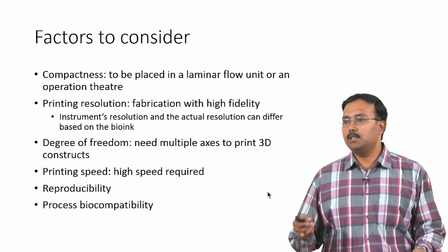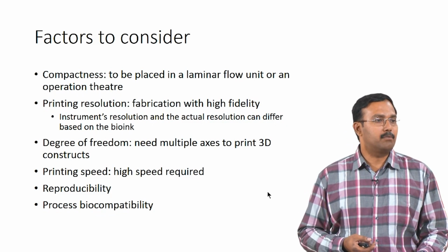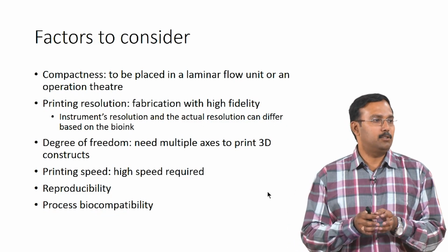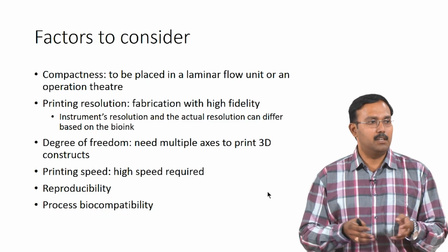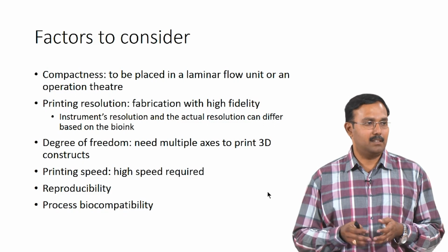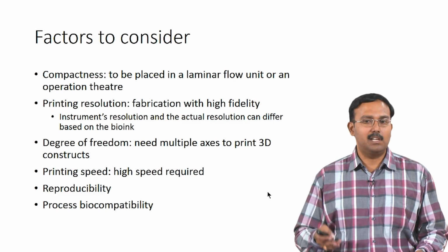So, that reproducibility needs to be there, and the process biocompatibility should also be taken care of. Biocompatibility of the ink is one thing, the process itself can actually kill the cells, right. So, for example, shear or temperature. So, inkjet, if you are going to use a thermal kind of DOD, then there can actually be high temperatures used which could kill the cells.